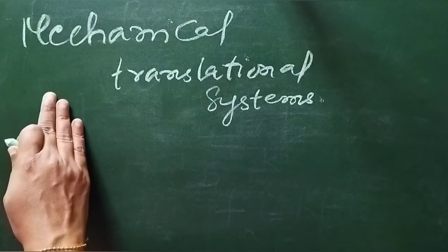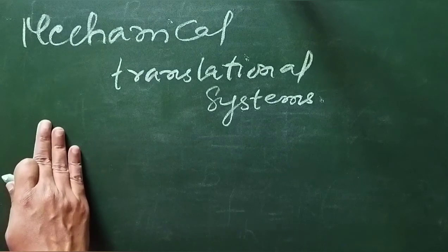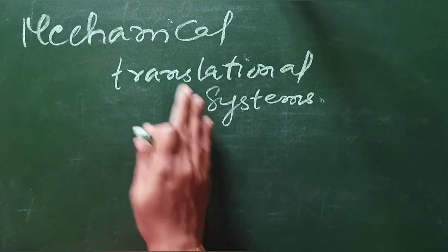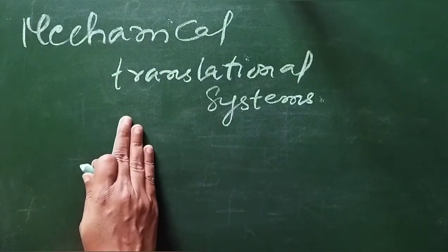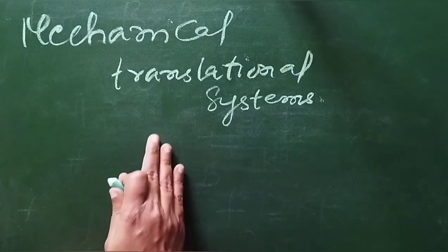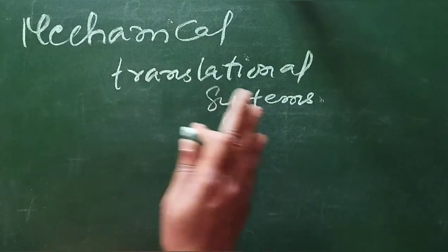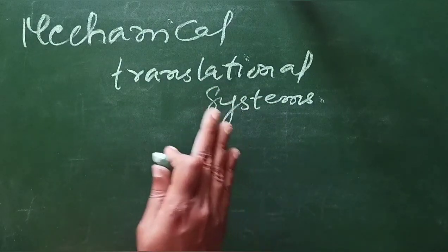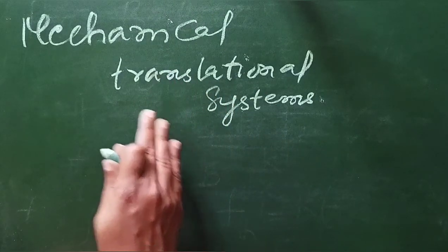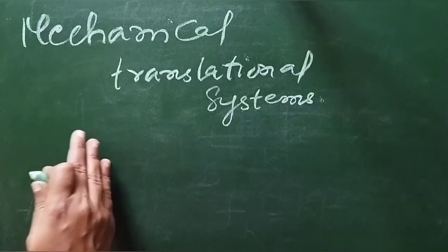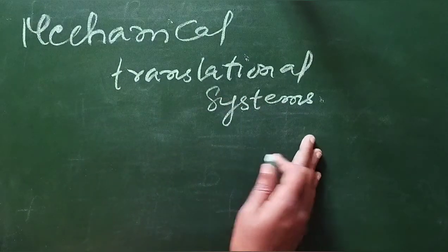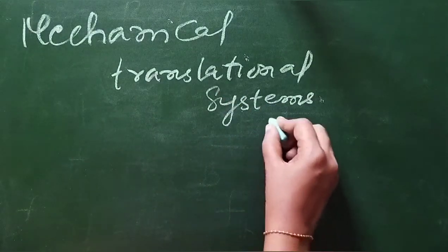Now once we come to know about all the parameters involved and the individual elements' representation, finally, once you have the combination of these elements, what we do is first frame the free body diagrams of the different elements at those particular nodes, represent the force and the displacement, draw the free body diagram, and then apply the condition applied force equal to opposing force at each and every node. Usually those nodes are nothing but the mass elements.